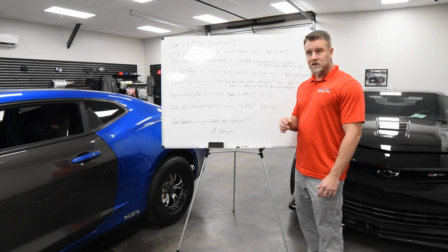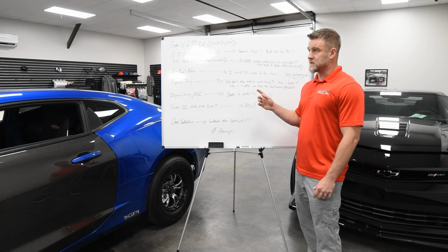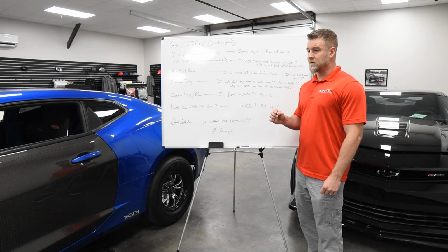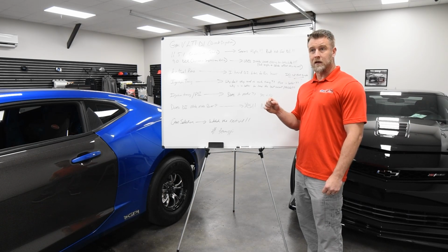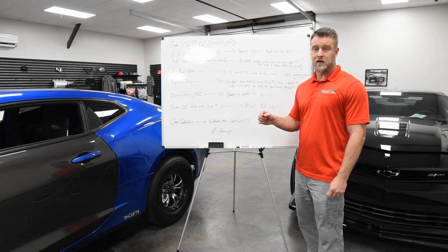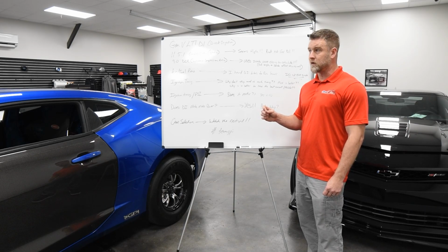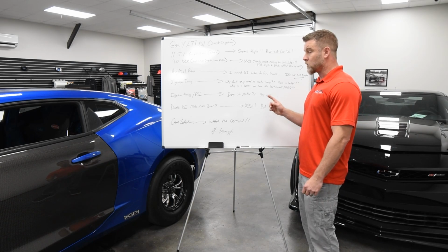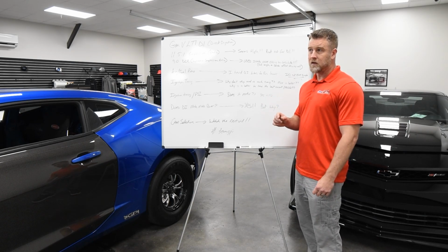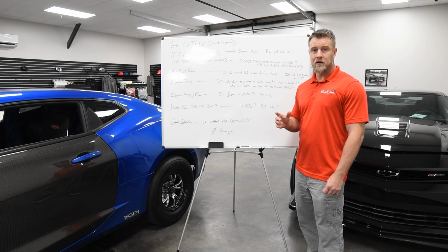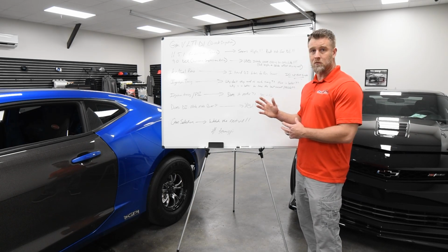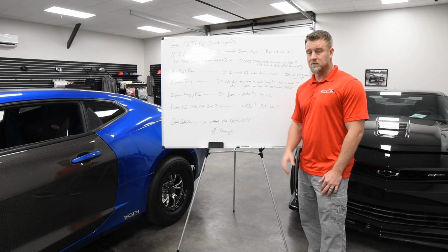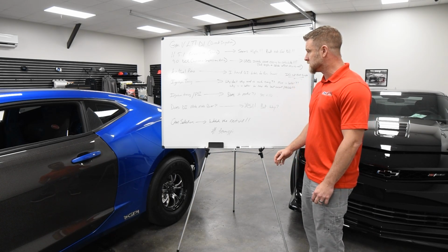The LT stuff likes nowhere near that. I've never seen one of these like more than about 28 degrees of timing on the E85. And some of our best performing NA combos with our CID LT heads are down there around 24 and 25 degrees on the E85. So this is a case where more is not always better. It's relative to the combination and this platform. They just simply do not need the ignition advance that the port injected engines do in most cases.